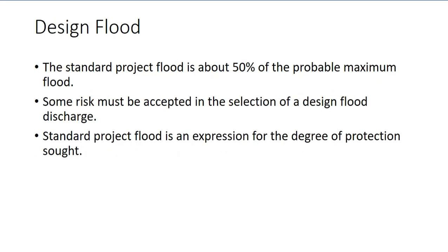The design flood, the standard project flood, is about 50% of the probable maximum flood. So when you design a project or a future flood project, you should provide up to 50% of the probable maximum flood.